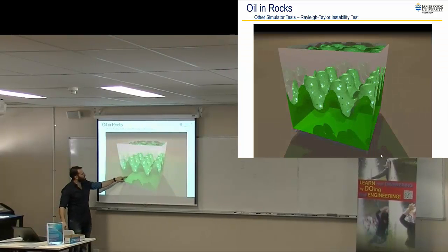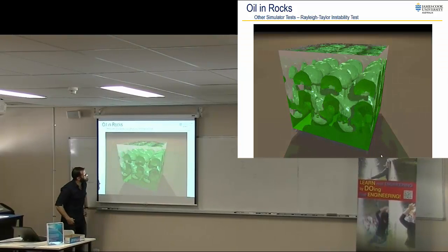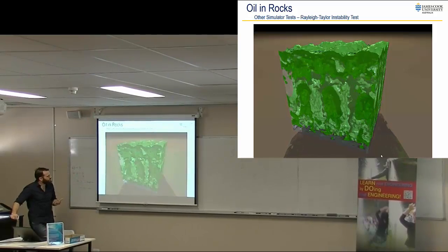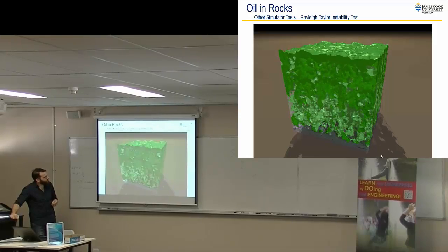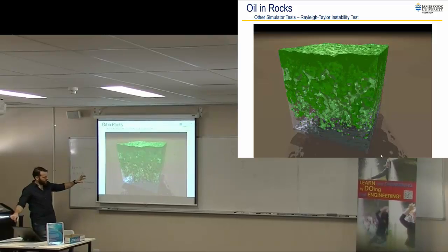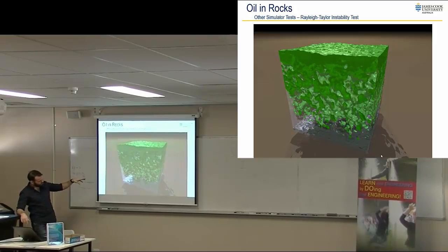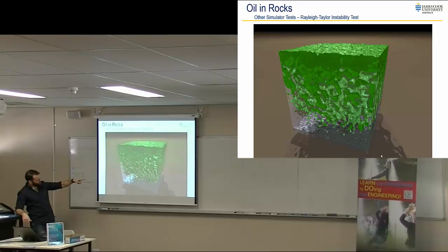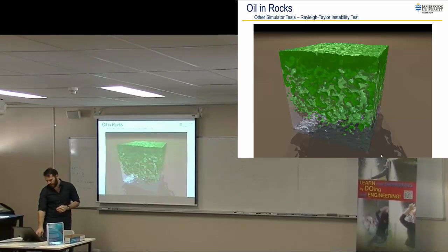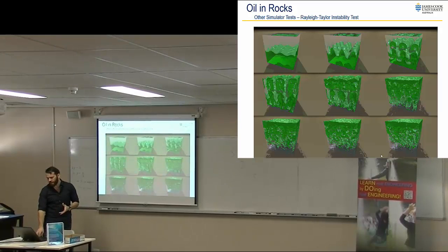This is oil and water and a surface, and obviously oil wants to rush to the surface of the water. This is something called the Rayleigh-Taylor instability, which is a very common profile in terms of how the two fluids interact. And the advantage of using the particle method that we do is that it takes into consideration all of those little interfaces kind of naturally, whereas a lot of the other codes that you might use, you have to put a parametric surface around those and calculate where that moves, and it's very costly. So that's another little simulation that we can run with the particle codes.